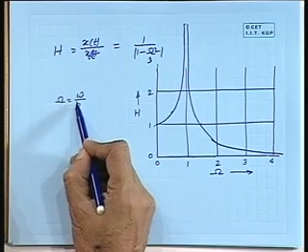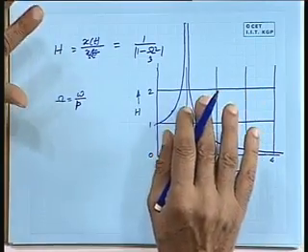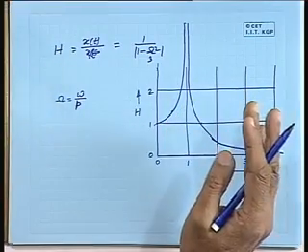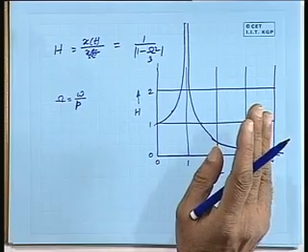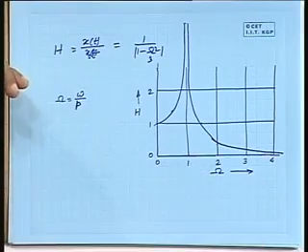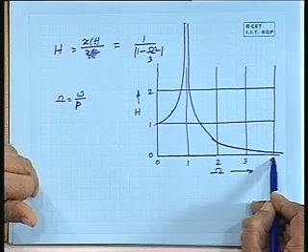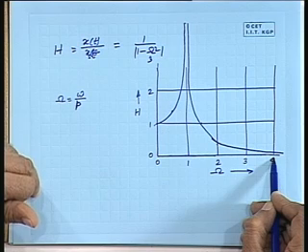Now, this p, the natural frequency of the object or the structure on which this is mounted, may be say 3 hertz. Now, 3 hertz is around how much? 180 rpm, okay, or say 30 hertz, so 1800 rpm. So, you are starting from 0 going up to say 70 to 100 rpm. So, 0 to 4 it is going, frequency ratio.